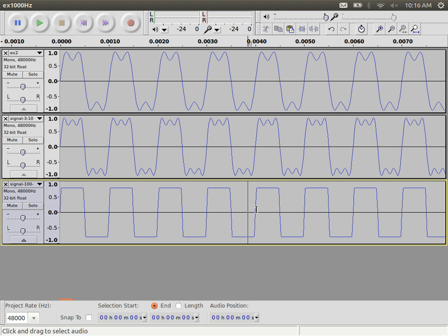This 100 component signal gives us the same data rate. They all give the same data rate of 2000 bits per second, all three signals. But this 100 component signal uses a much higher bandwidth. That's the problem. The top signal uses 2000 Hertz, 4000 Hertz. I can't calculate what the exact bandwidth is, but I think it's almost 100 times what we have here, 2000. So it's much higher bandwidth used.